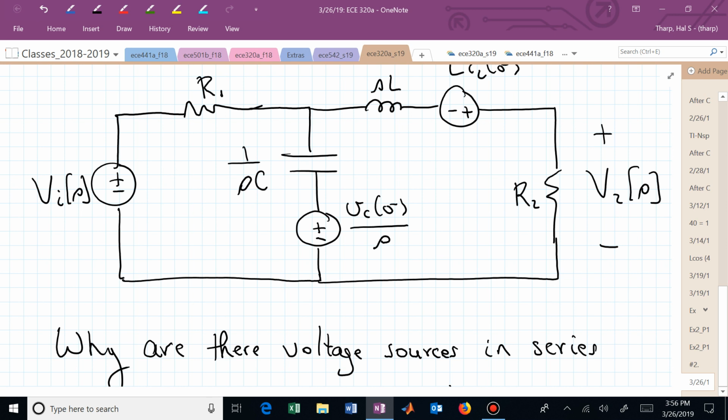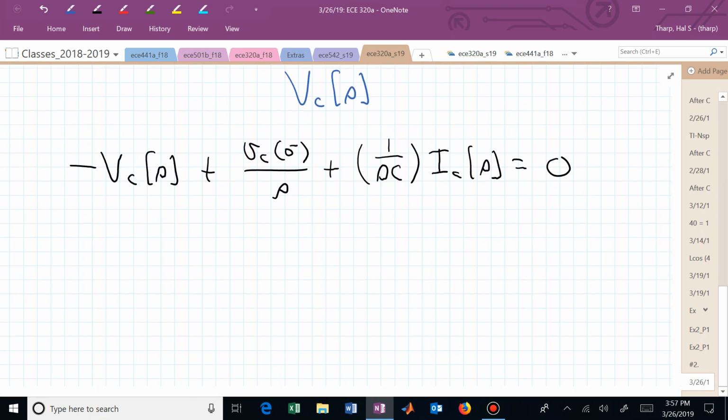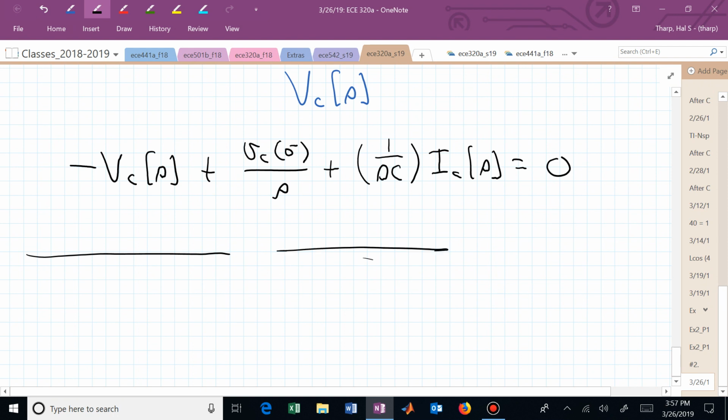If we then had that voltage initial condition on our capacitor, we now have a plus minus, and you can see it doesn't really matter whether the voltage source is below or above the capacitor, the analysis will be the same, as long as it's in the same series branch. What about these resistors? So that's how we can justify the S-domain equivalent circuit for a capacitor, any capacitor.